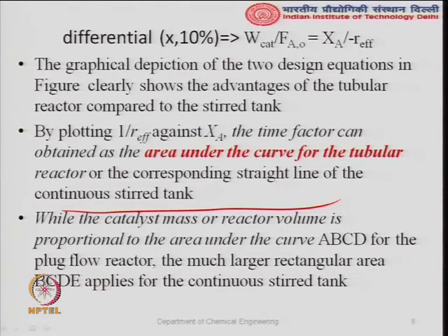So, this is very important in terms of reactor design. One should go with a plug flow reactor or select a CSTR, that becomes important. Sometimes a combination of the two can be used, a recycle type reactor. Or a fluidized bed reactor or slurry bubble column reactor, which are commercially used, because if mixing is an issue, heat transfer is an issue, you cannot use a plug flow reactor. You need to dissipate the heat from time to time.